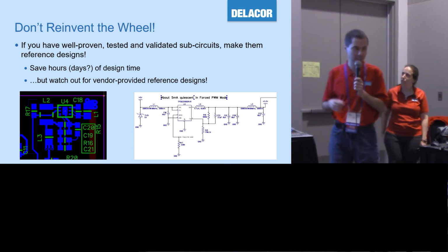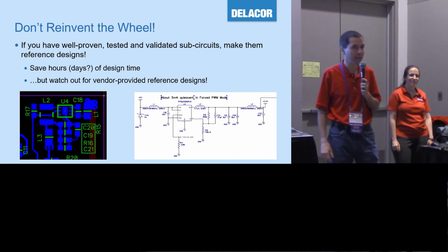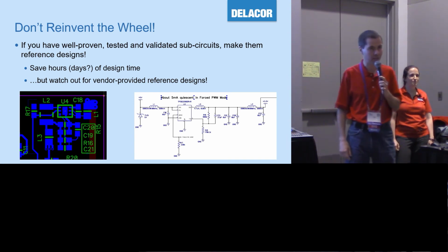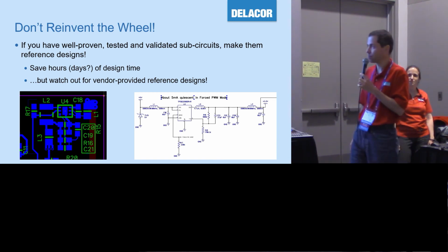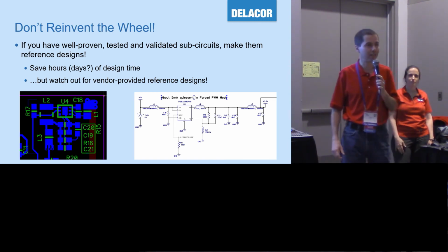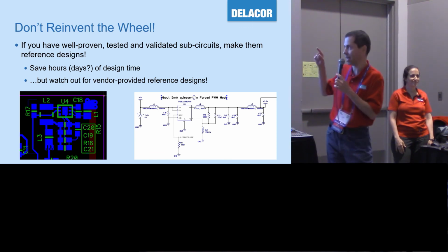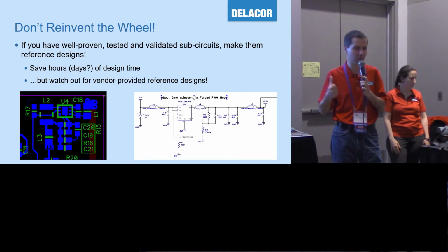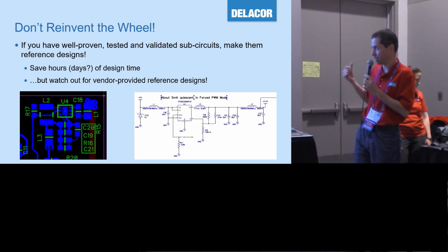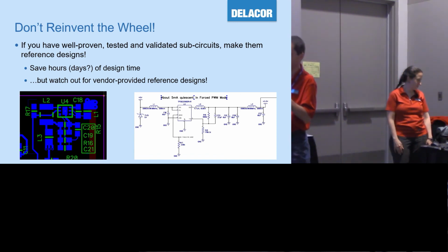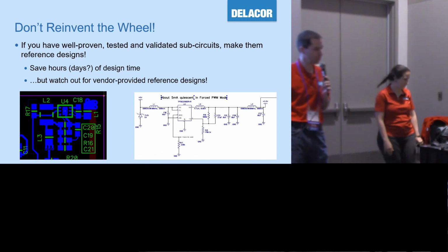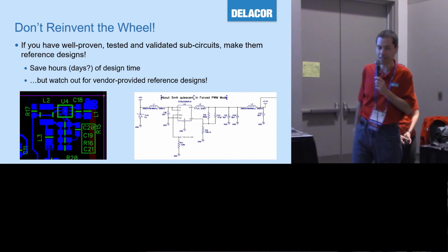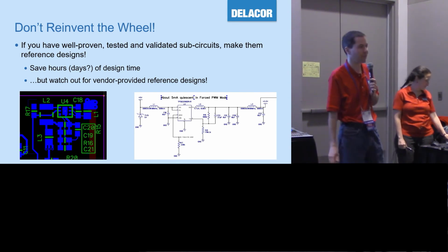You can get reference designs from vendors, but you have to be very careful because the goal of the vendor is to showcase their part and to sell their part. That doesn't mean that their reference design has your best interest in mind and that it is going to have the robustness requirements or maybe the temperature performance that you need. They're going to pick all the components around their part to make their part look good, which probably means they're going to be expensive. You may not need that. So vendor reference designs are great, but you really have to understand what they're doing before you just take them as is.